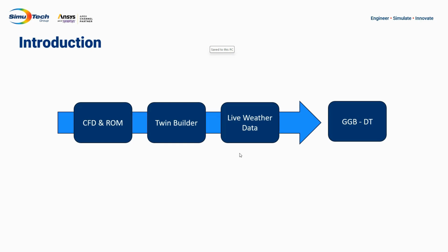First, we explored how to put in a constant as well as a data set, and then reading the live data, either first reading it and saving it to a CSV file and then making the Twin Builder model work on that, or creating a twin model, extracting that from Twin Builder, and then putting it into a separate Python code, utilizing that, reading the live data, and collecting the results immediately. Thank you for watching.